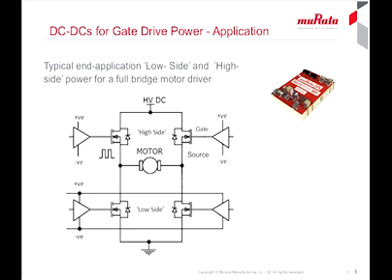Looking in more detail at a high side switch, you can see that the PWM signal is isolated, typically through an optocoupler, and the power rails for the driver are isolated through a DC-DC converter. This allows the 0-volt return on the DC-DC converter output to float and be connected to the source of the MOSFET, which is a switching node. If you connect an oscilloscope from the DC-DC converter input return to output return, you would see a continuous pulsed waveform with an amplitude of the high voltage power rail.